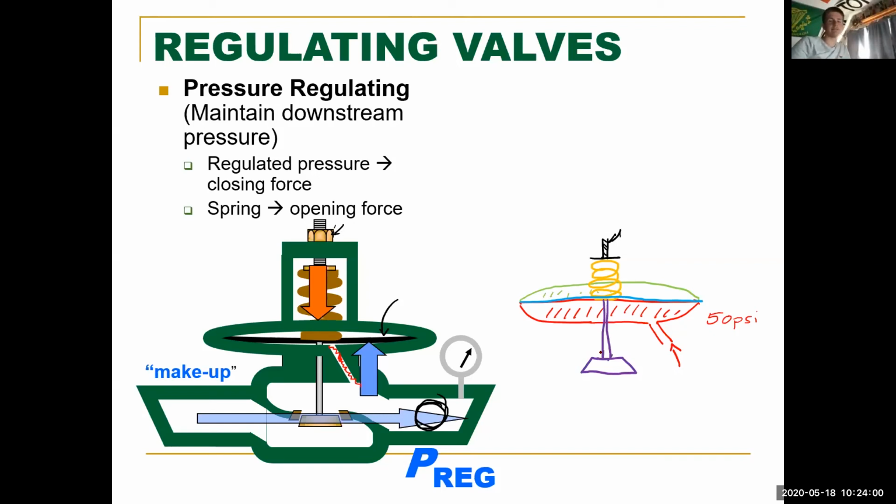No. Like, why not? Is it when the spring is not able to handle that, or maybe we just have too much regulation with that spring? Let's say the spring can handle it. Okay, so what's going on here if we look at it? We have the spring that's pushing downwards, right? So the spring is going to be regulating it. But the other thing we have to look at is which way the seat is facing. So it's seating upwards. So it's pushing up.